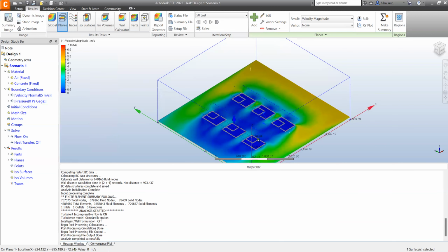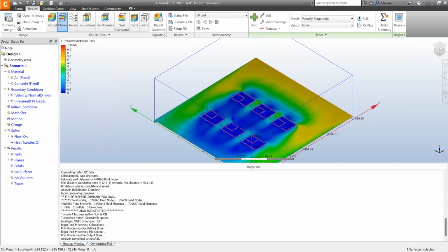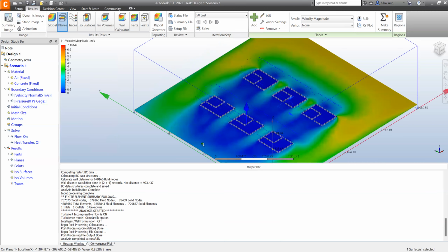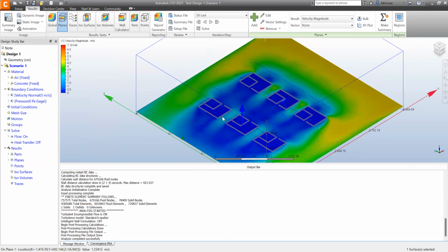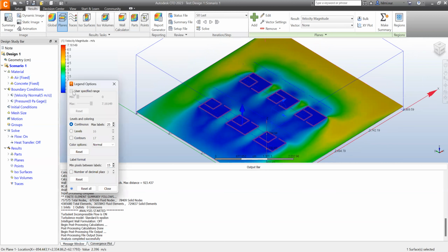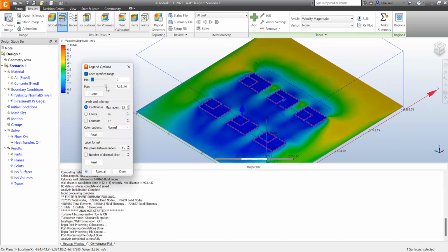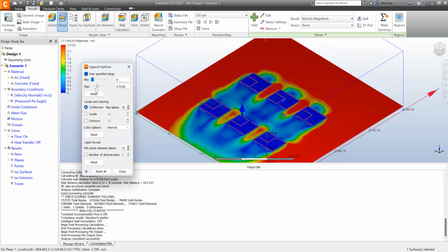And if we want to check more detail, like maybe from the range 3 until 0, mostly for the interior, because on this part we see all of this part is blue, so we couldn't define it properly. We have to change the range. To change, just click option, and then click user specified range. The minimal still 0, but the maximum could be changed into the lower one.